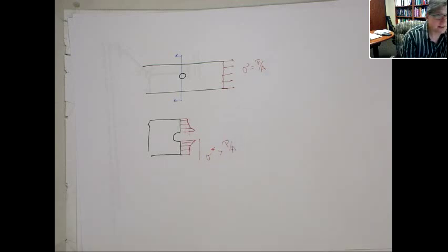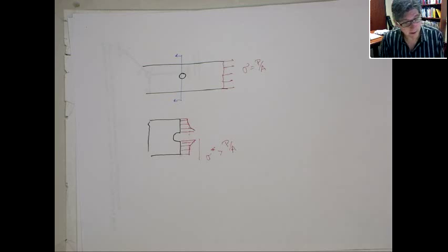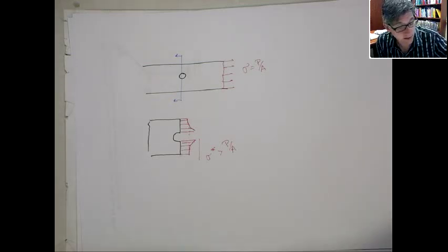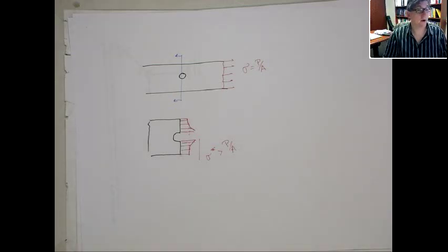Now these factors happen all the time, and obviously when we're talking about a design situation and we want to know when the structure fails, we actually do want to know the peak stress, because that's often where the failure will occur. And if you design to a lower stress, even if you do have a factor of safety, that can cause issues. So, obviously, factors of safety help take into account some of those things. But when features are large enough, we can actually have a more accurate approach.